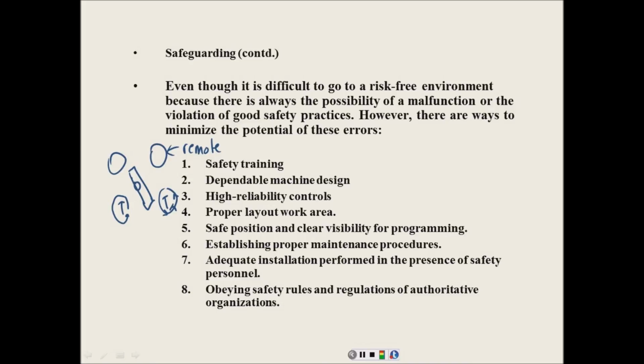Remote means we turn over the control. In a lot of those videos you saw, the people didn't use the teach pendant. If they had a panel up there where they hit play or stop or whatever, that's what we call a remote panel. A lot of times they don't even make the teach pendant available to the operator, because they don't want the operator to be able to select programs or do things that could cause problems. So they'll set up a remote panel that has very few buttons on it. It usually has a run and a stop, and then fault indicators, and usually a button where you can reset faults and stuff like that.